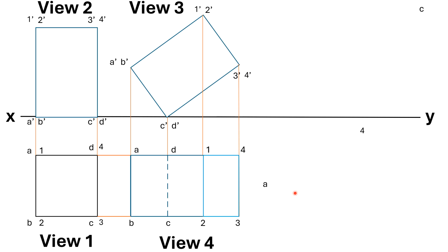Now according to the problem, this solid is also making some angle with the vertical plane. When the angle is making with the vertical plane and this true angle we can able to see in the top view. So here now this axis is making the zero angle with the vertical plane. So axis, let us say here, and the axis is parallel to this edge, or otherwise we can say axis is parallel to xy line. So it is 0, so it is parallel.